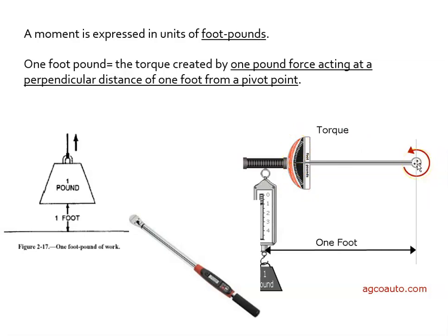And manufacturers will often specify, they'll say, tighten this to a torque or a foot-pound rating of so many foot-pounds. And at that point, whoever's fabricating or building whatever is being built would take out their torque wrench and tighten up all the bolts to that number. Okay, so that is a foot-pound of torque.